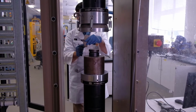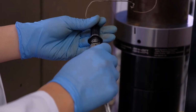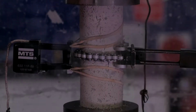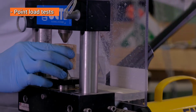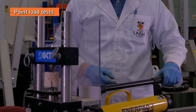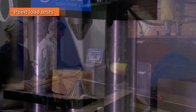UCS test data is further used for the determination of appropriate powder factors for drill and blast planning, and for the determination of site-specific sonic UCS relationships to reduce the need for laboratory sampling as operations become more mature. Point load tests are required for the determination of rock mass strength, conversion to UCS strength in the absence of UCS tests, or to supplement UCS test results.